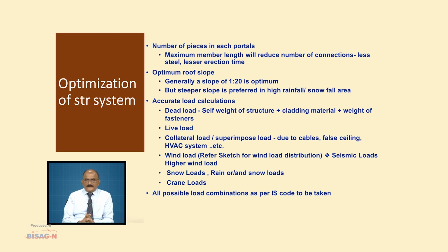And for wind load, seismic loads are also to be taken very correctly. Snow loads, rain loads, crane loads, what kind of crane being used, all these things, all the loads to be taken into consideration, and all possible load combinations as per IS code shall be taken.